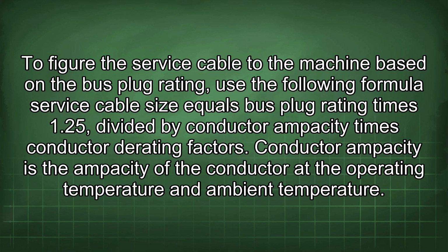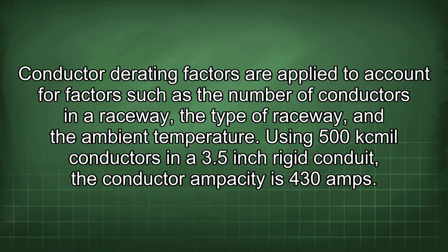Conductor ampacity is the ampacity of the conductor at the operating temperature and ambient temperature. Conductor derating factors are applied to account for factors such as the number of conductors in a raceway, the type of raceway, and the ambient temperature.